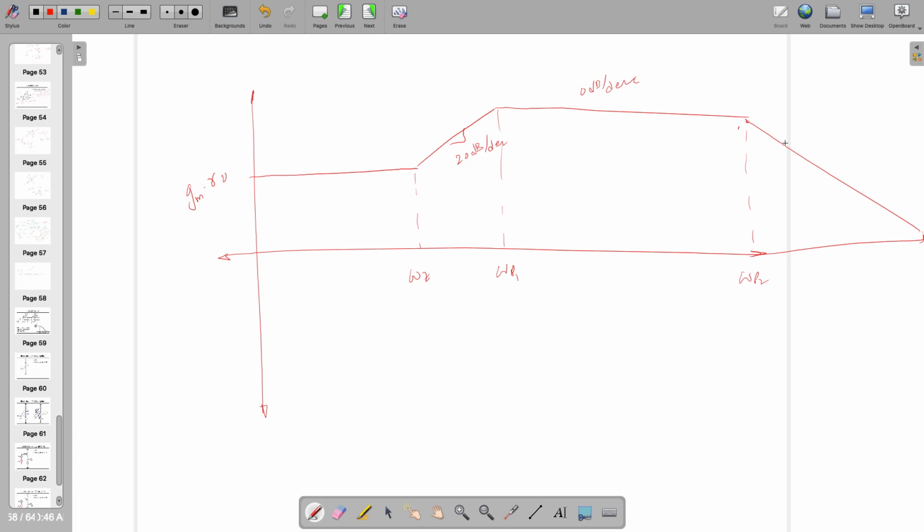And effectively, if you look at this, zero and pole cancel each other's phase possibility. Here also, the phase margin will be plus 90 degree, because this is going to give you 0 to plus 90 degree and this is going to give you 0 to minus 90 degree, effectively adding both of them is going to give you 0 degree at the end. Afterwards, you're going to see the phase by omega p2 as 0 to minus 90 degree and the phase margin equal to plus 90 degree. So this is happening all because of where you are keeping the poles, and this is very important as a designer, to place poles and zeros at the according position.